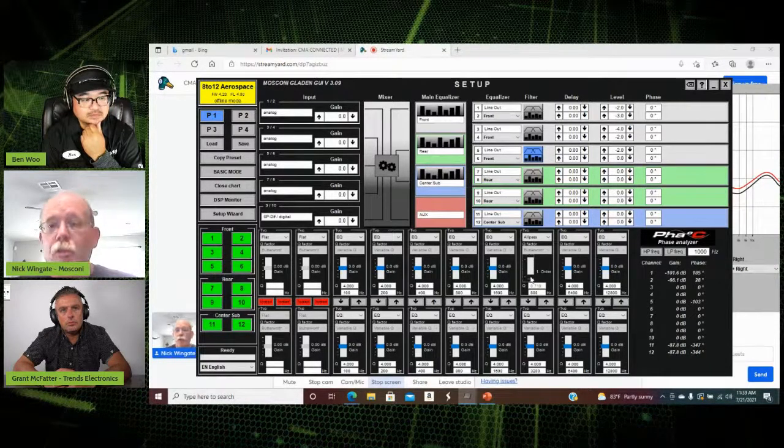What you'll do is run a sine sweep between the left mid-range and the center channel only. And you find the null between the two of them, and I guarantee you it's going to be somewhere around 300, 400 hertz, somewhere in there. And you run a second order all-pass filter, and it will correct for it, and you don't have to do anything else. And on the right-hand side of the car, do the exact same thing.